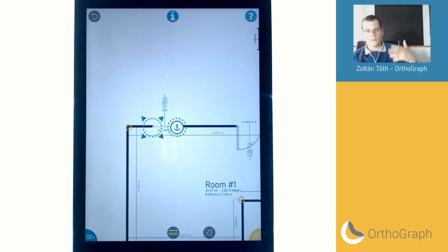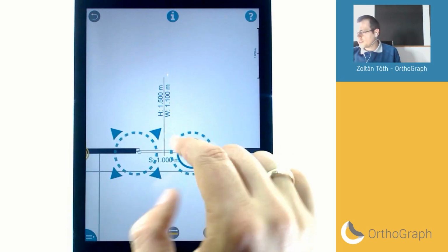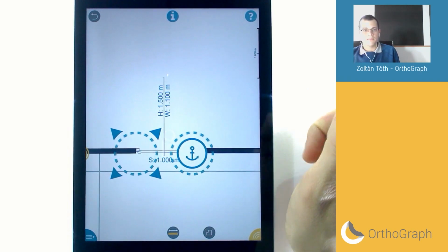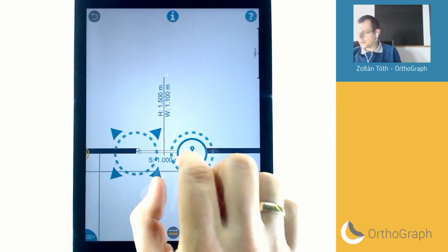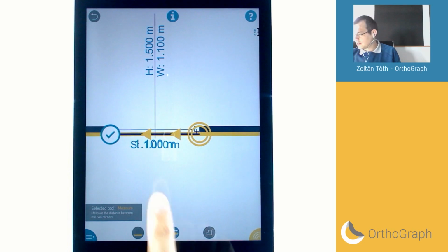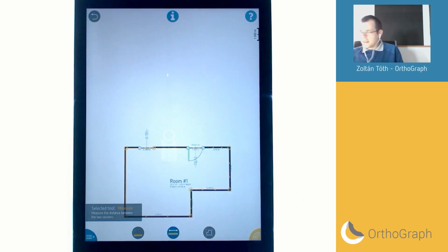So if you are looking for a CAD format as an export format from this drawing, then I mainly use DWG here. Oh, we support DXF, but that can also be read into most DWG compatible software such as AutoCAD, Revit, or ArchiCAD, all these kind of things. So what you are going to get if you export this drawing into DXF is that you are going to have this opening stamp which would tell you more about the sill height. There you go, you see it at the bottom, the sill height.